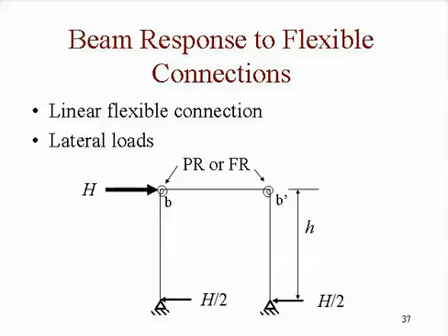They aren't going to be simple, because if they're simple connections, it's laying on the ground, right? So they have to have some moment capacity. We don't even need to know what those connections are capable of doing, as long as it's symmetric, to know that that horizontal force H is distributed H over 2 and H over 2. So this is a fairly simple thing to analyze.